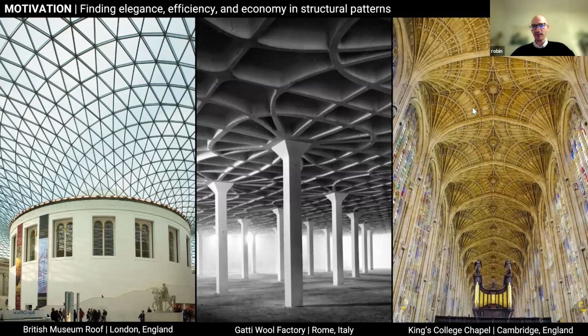They're not necessarily meant to carry higher forces once it's built, but they're meant to be assembled first. So you first build a centering, a set of wooden elements. You can put the stone blocks, the voussoirs that make the arch, so a light arch supported by this centering. Then you can span in between.